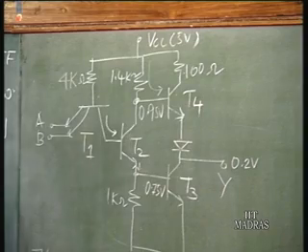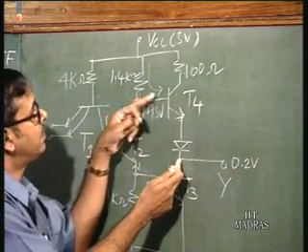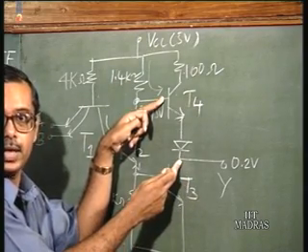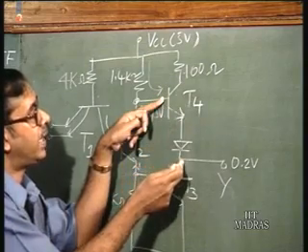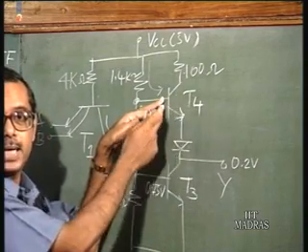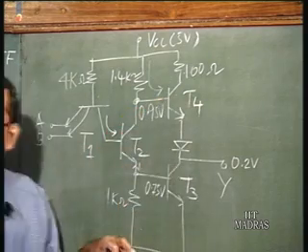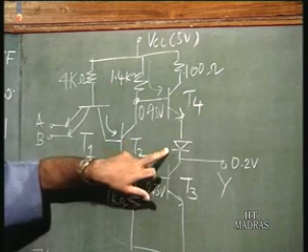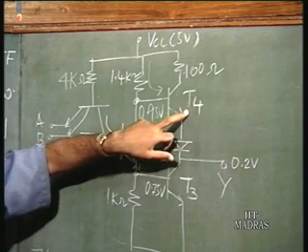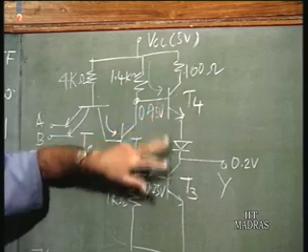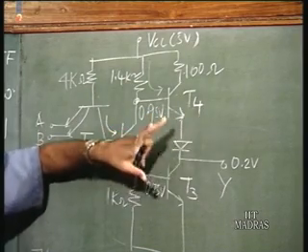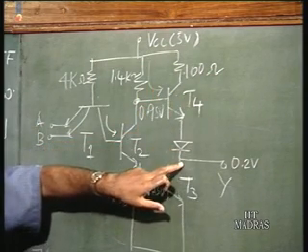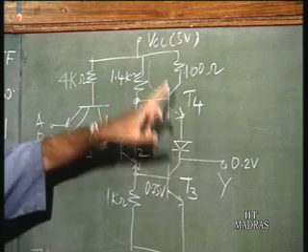All right. So you have a drop of 0.75 volts between the base of T4 and the collector of T3. So you have a 0.75 drop shared between the base-emitter of T4 and this diode here. This actually explains why we require a diode here. If the diode was not present, this transistor would never have gone off. But now this 0.75 volt is shared between these two PN junctions, so neither of the PN junctions can turn on. So this is going to be off. So basically at the collector of this transistor T3 you see a very high resistance.